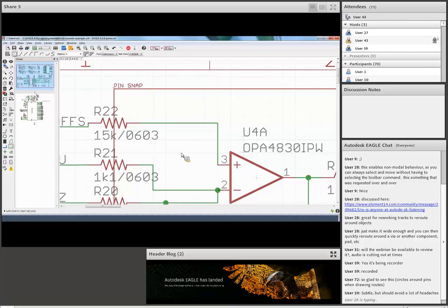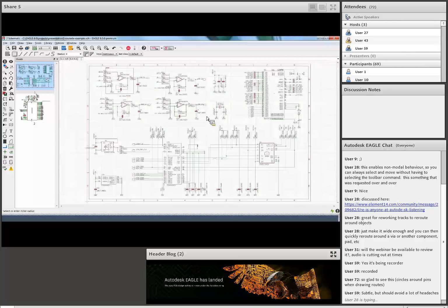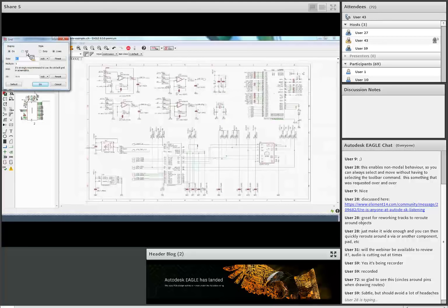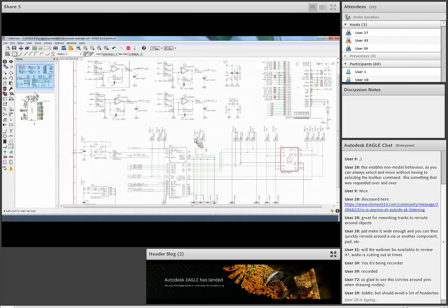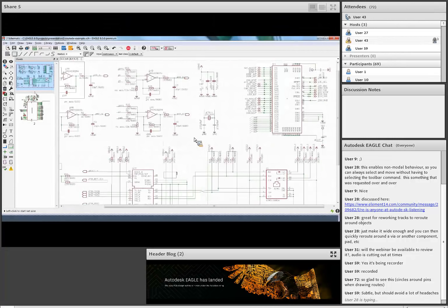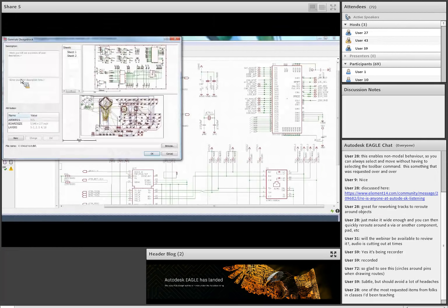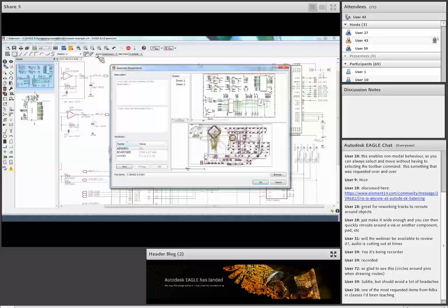Okay, I'm going to go ahead and zoom out and turn off the grid. There's too much information currently active right now. Okay, now there's two modes for design blocks. If I click here on the down menu that says File, and I click here where it says Design Block, it actually allows me to save the entire schematic as well as an entire board as a design block.